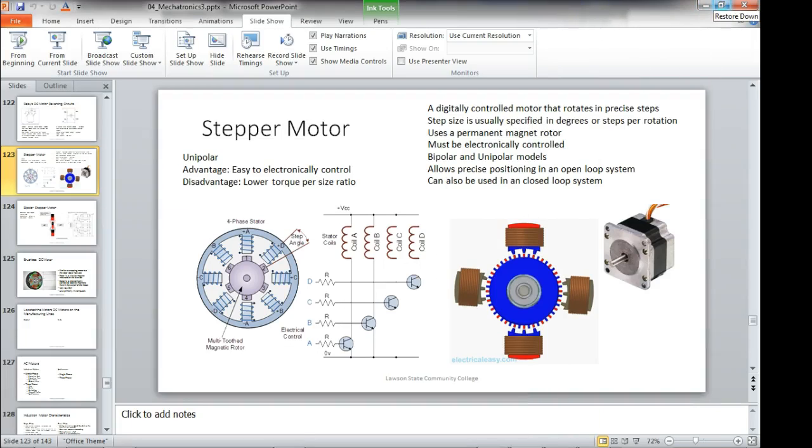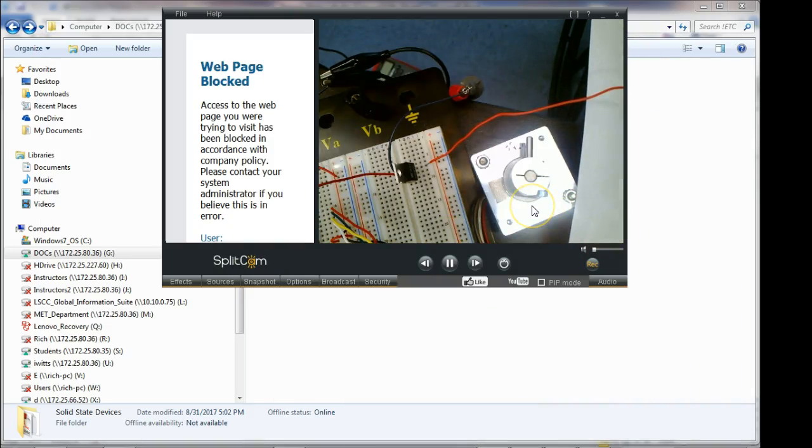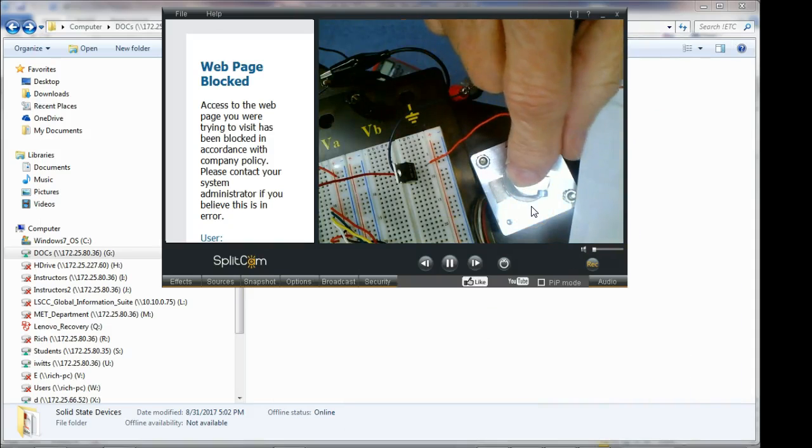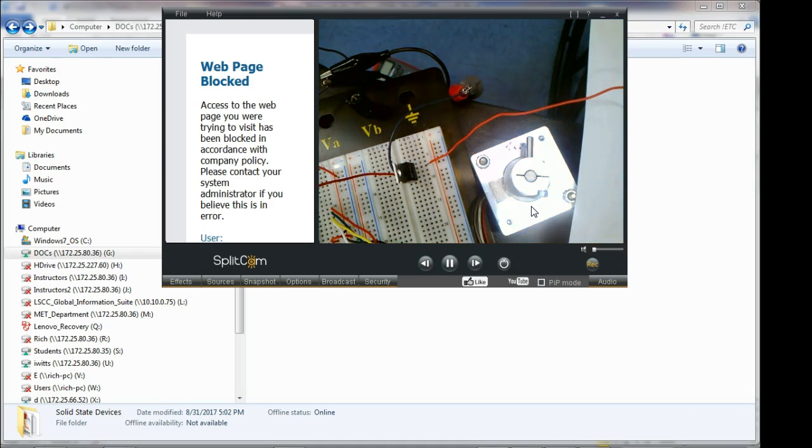The biggest problem we have with DC motors is that commutator. Every time it switches, it gives a little spark, and when it sparks, it generates a lot of electromagnetic interference. I've got another motor up here called a stepping motor, which I'm going to show y'all in a minute. You can see it picking up the noise.